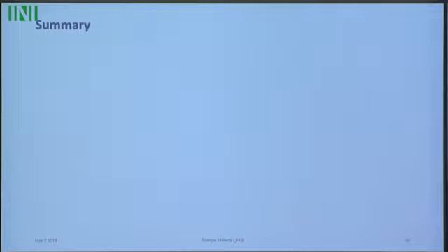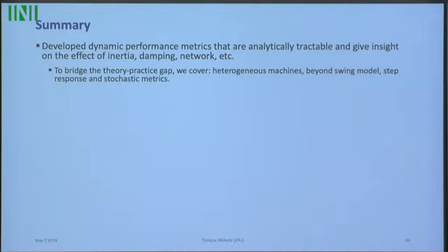I think I'm going to wrap up here. What I presented is a stylized system in which we try to understand the role of inertia, the role of damping, and the role of different controllers to actuate in this system. We defined these metrics, and we were able to compute them in a rather generalized case of proportional parameters. And we compared all these different parameters and saw how they affected the performance of the system.